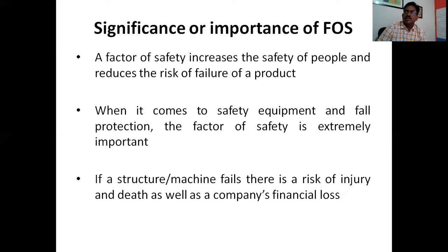For example, when a company has gone for a major project, whatever the project may be, if anything fails, it's a loss to the company and a loss to its reputation also. That's why this factor of safety is very important from the point of view of safety as well as protection and financially also. That's why the design stress or allowable stress should always be less than the ultimate or yield point stresses of a material.